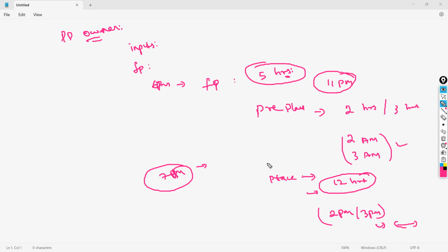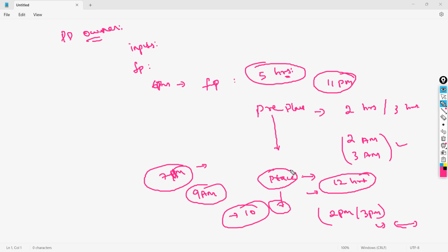But what happened is you did not have that, you're just firing the runs one by one. So you got up and by the time you log in it is 9 a.m., and you fire a run, it comes at night, midnight, 10 o'clock again. So you need a flow where once one stage gets over, the other stage automatically gets started, and the same thing continues, and it checks certain prerequisites, such as whether all the files that are needed for your placement are present and things like that.